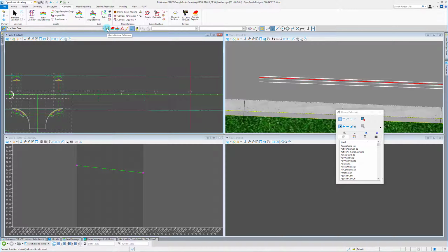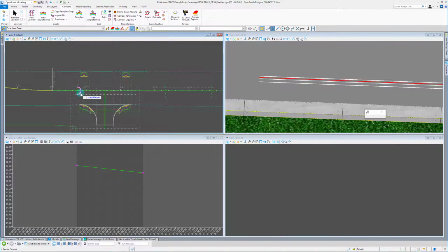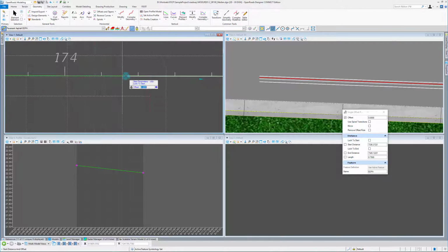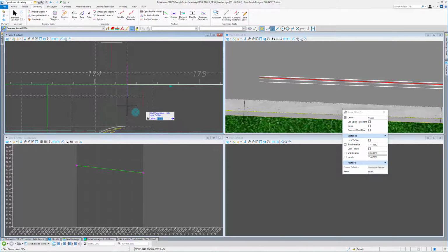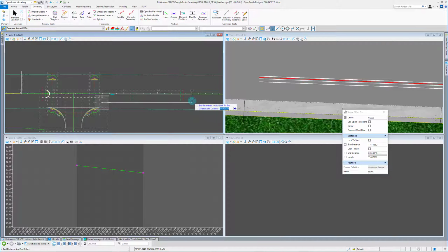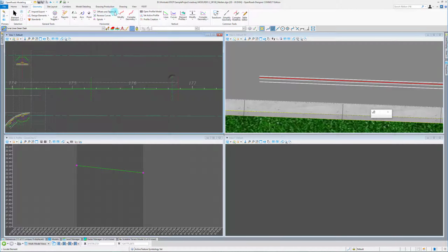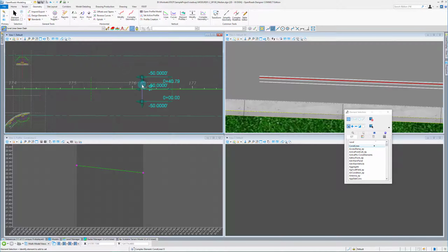So we're going to go ahead and we'll set up our edge pavements first. Single offset partial, and we're just going to write down the center line, and we'll snap it to here. And I forgot to draw a line. I need that end taper. Let's do that. So we got a 50-foot taper.